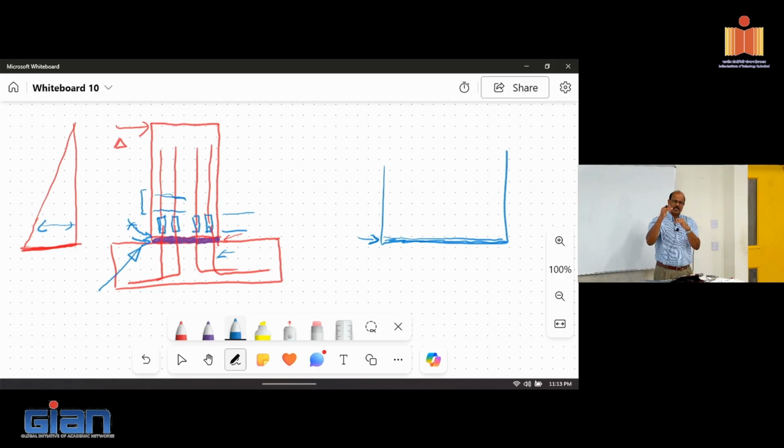So basically saying that your concrete strength of the wall should be higher than whatever the interface is. I personally don't like the idea. So in the committee we had difference of opinions. At the end we decided that grout pad should be stronger. So specifically the ACI document calls for stronger grout pad than the member itself.